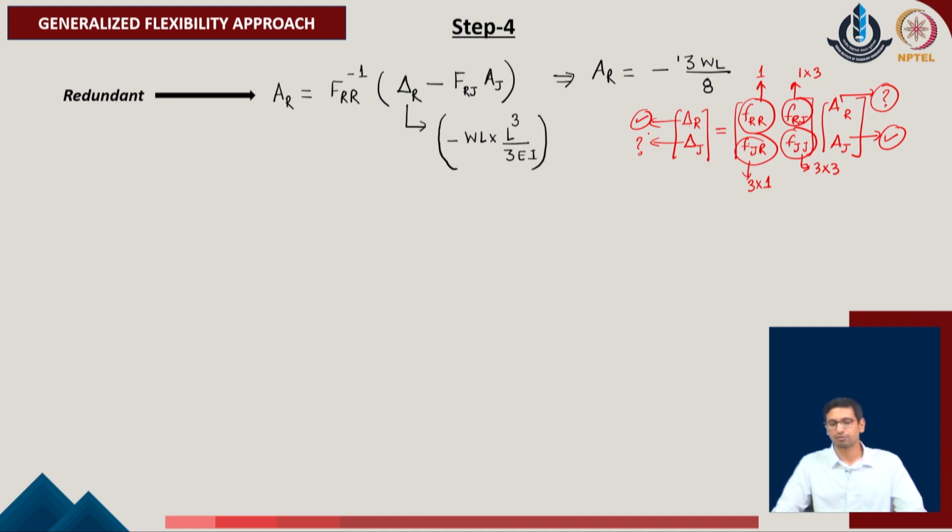Now, in order to calculate the value of delta R, we realize that while all the forces have been considered while writing the given set of equations, we have not considered the contribution of the spring in the given problem. The spring contribution will be considered with respect to the load which is active directly at that point. One must note very clearly that in order to calculate the delta R value, we have not evaluated the component of A of R, because A of R has already been included by considering the contribution of the flexibility system.